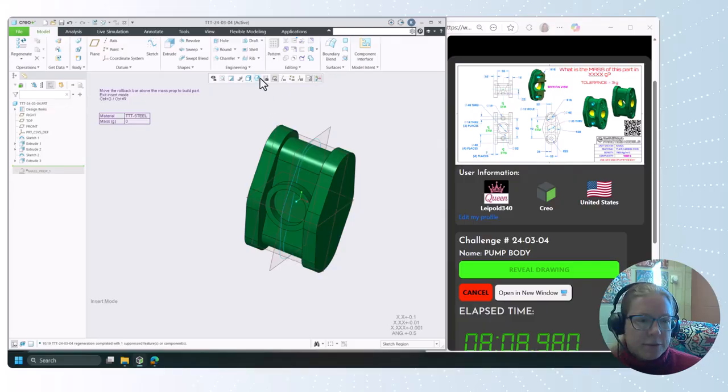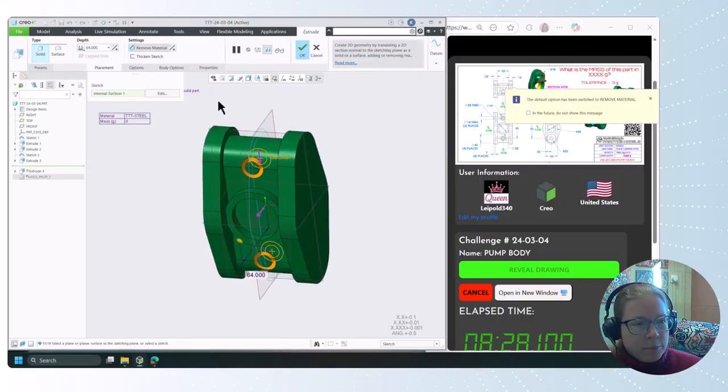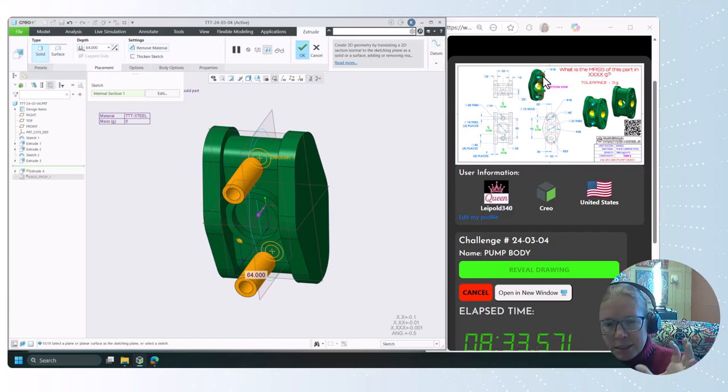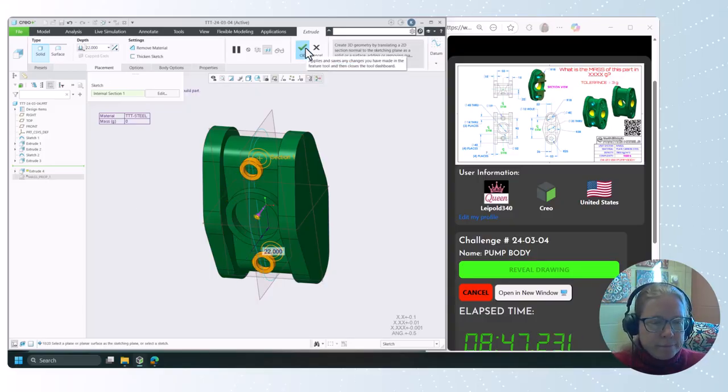Then if I go back to my front view, and I'm looking for the hole, right there. Again, a right click will do a quick cycle. And then I'm going to hold down Control and get the other one. We'll extrude those. Those are also going to add material, but those are only going to be one-sided, right? You can see it in the section view that it doesn't go out the back. The depth of those is 22, which is shown in this side view at the top. So those are just going to come forward with that depth of 22.